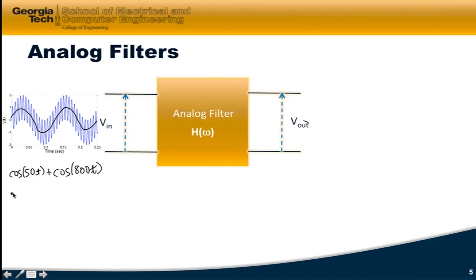Now, if I had a signal of an amplitude A_in cosine of omega 1 t into my circuit, and I got an output corresponding A_out at that same frequency plus maybe some phase lag, I can relate the input and output amplitudes, and they're related through this transfer function. So the output amplitude is equal to the input amplitude times the magnitude of the transfer function at that frequency.